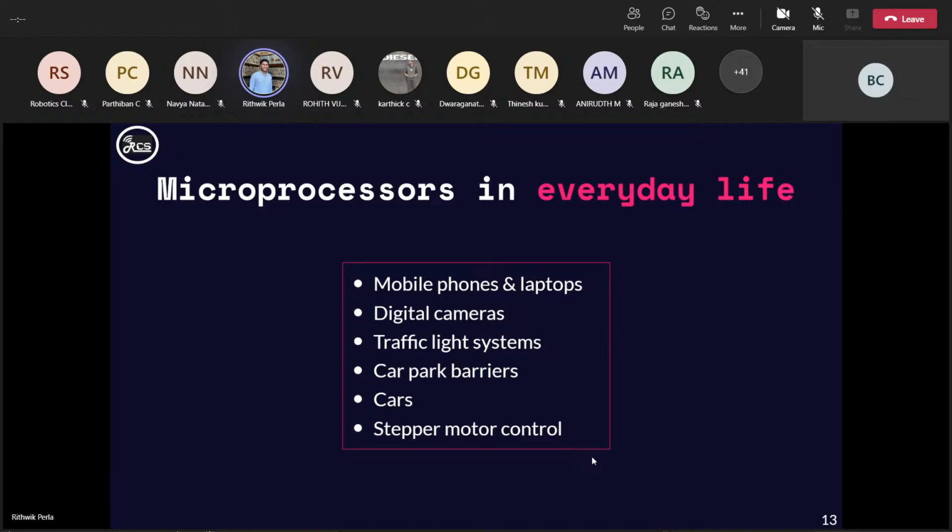So when you set it as 1 degree for every step, suppose you give the number of steps as 100, then the motor, after every time gap, will rotate 1 degree, wait for 1 second, rotate 1 degree, wait for a second. So it is in the form of steps. Work, pause, work, pause. That is how a stepper motor works.